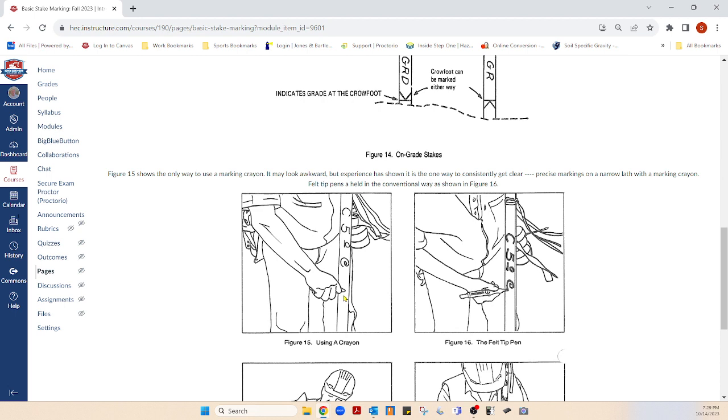This is just how to mark it. Nobody, I say nobody, used to use those lumber crayons like a big Crayola, but the felt tip is much easier. And notice how clear cut this is, and this is the way you write on a grade stake because you don't have much horizontal room. You start with cut 5 foot 0/10.